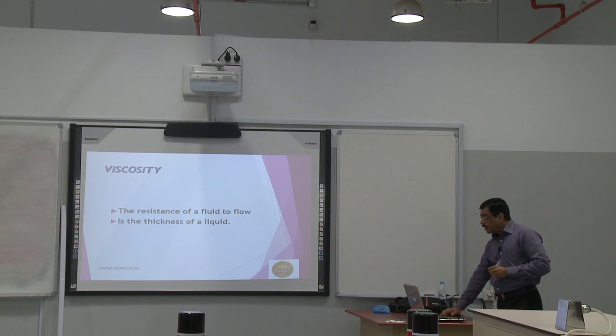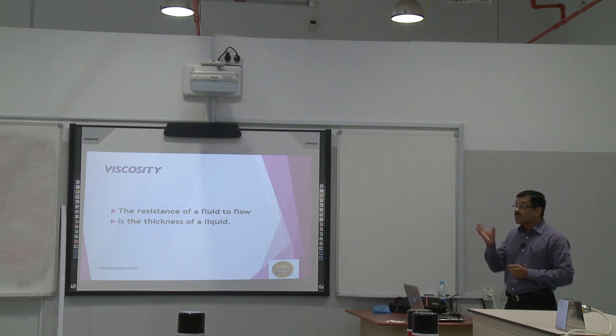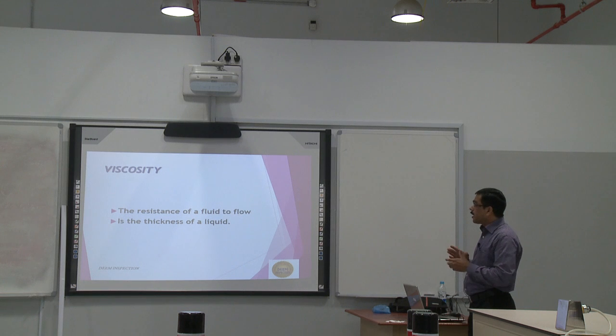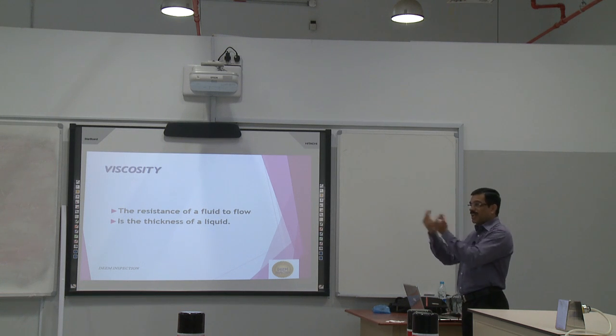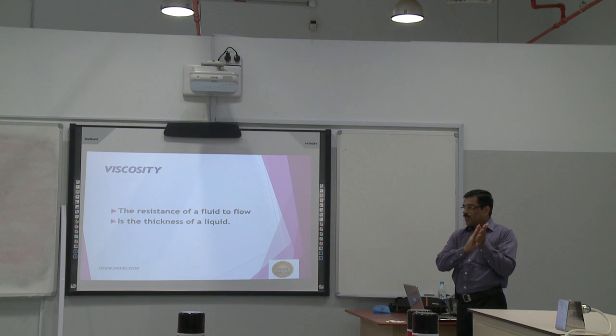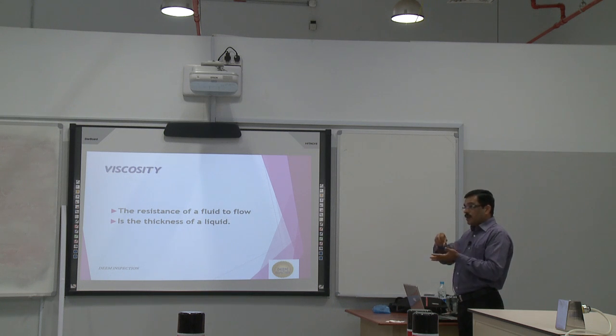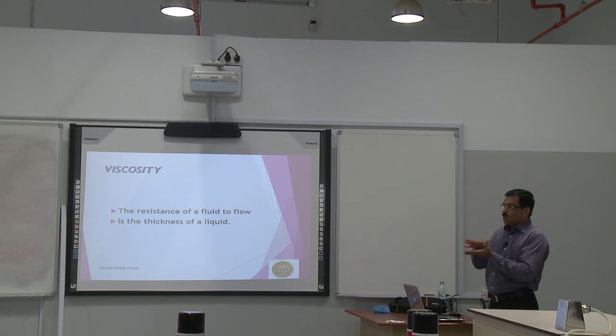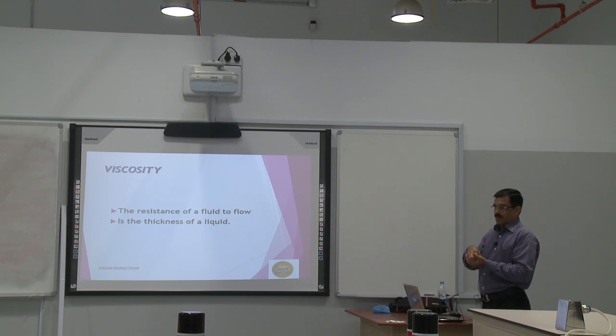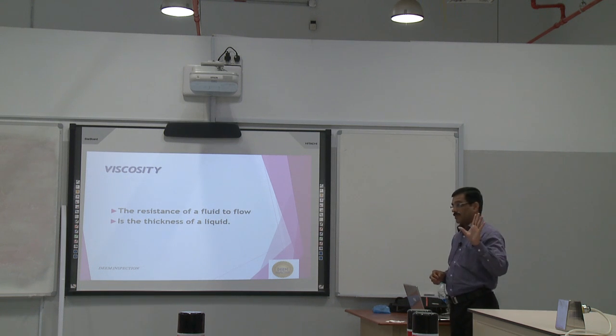And the last one we are talking about is the contrast ratio. Each penetrant should have some contrast, like black and white. Yesterday, to get the contrast in magnetic particle testing, we applied white paint, then applied black ink. The white to black contrast is very good, because white reflects all incident light, giving visibility, and black is just the opposite, it absorbs all light. So in this case, we are using the penetrant that is white.